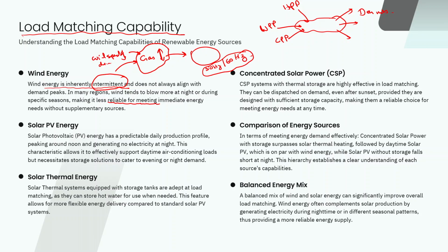So due to this varying power, you have to have some sort of mechanism to facilitate that, right? Sometimes you can use energy storage, and then from the storage you can dump to the grid, so you can regulate the energy you dump into the grid more effectively. But cost wise, that would be a very high cost solution.